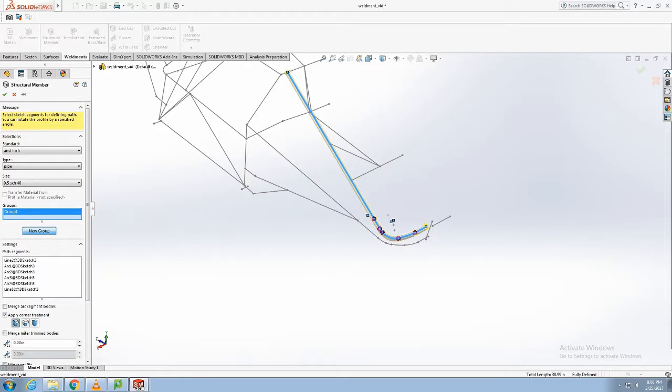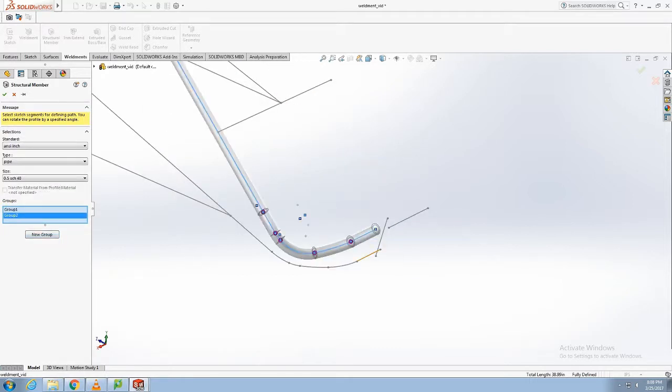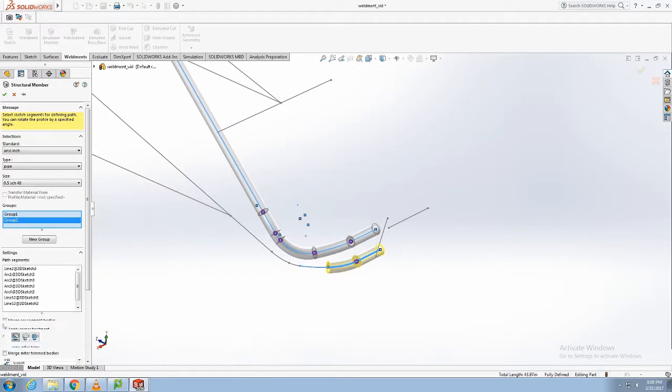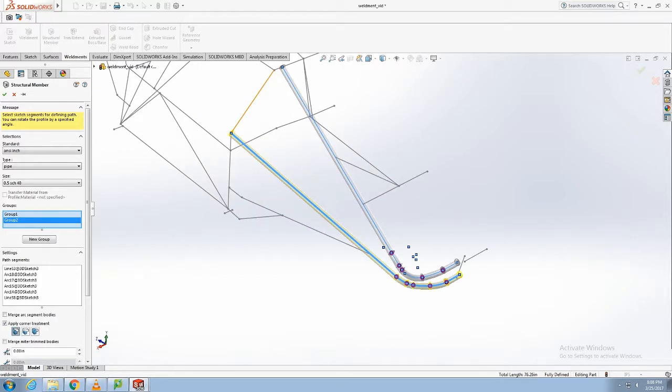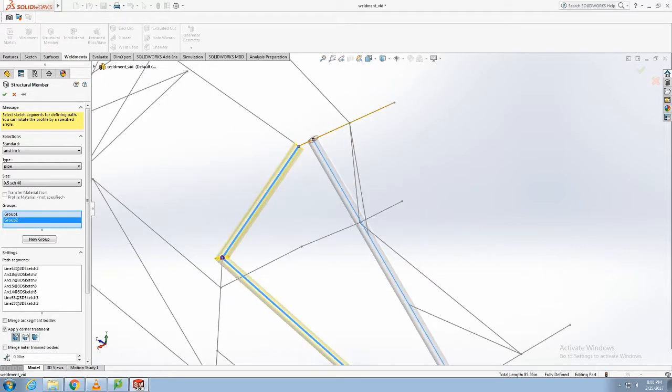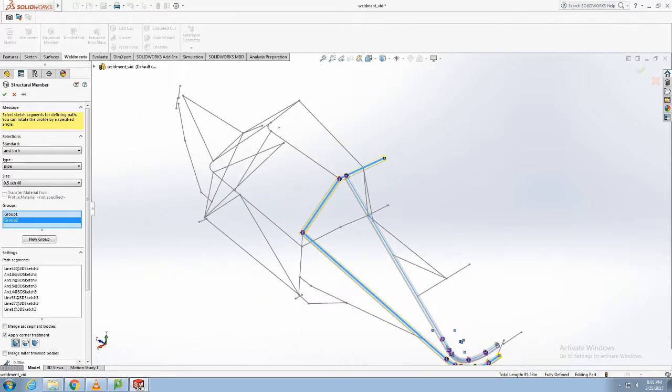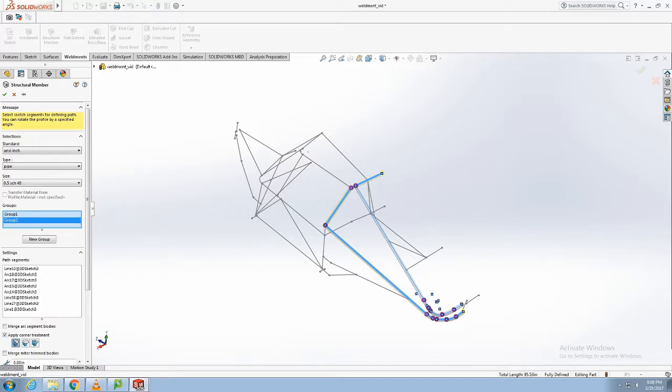Again, you'll be able to start clicking on more line segments appropriate for that grouping. This process is repeated until all the desired weldments for a specific weldment type and size are created. As the group list grows, the computer's implementation of the new weldments becomes much slower, so it could be advised to perhaps limit a specific weldment feature to the capabilities of your machine.